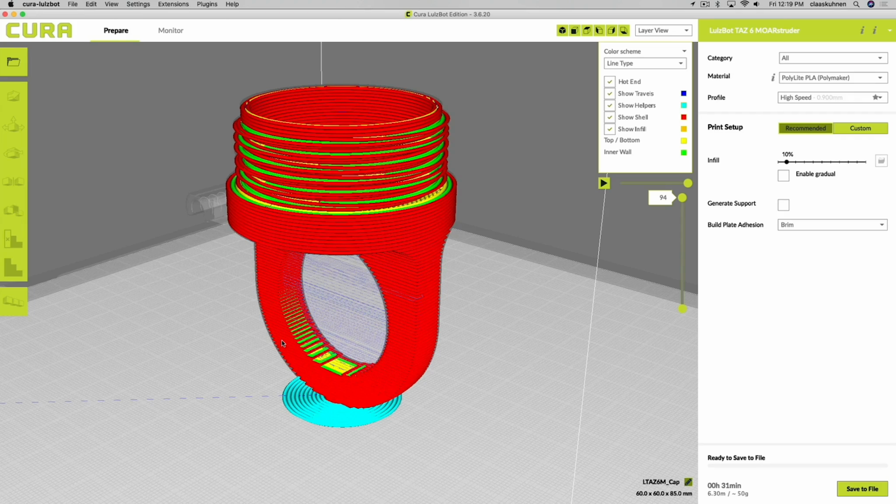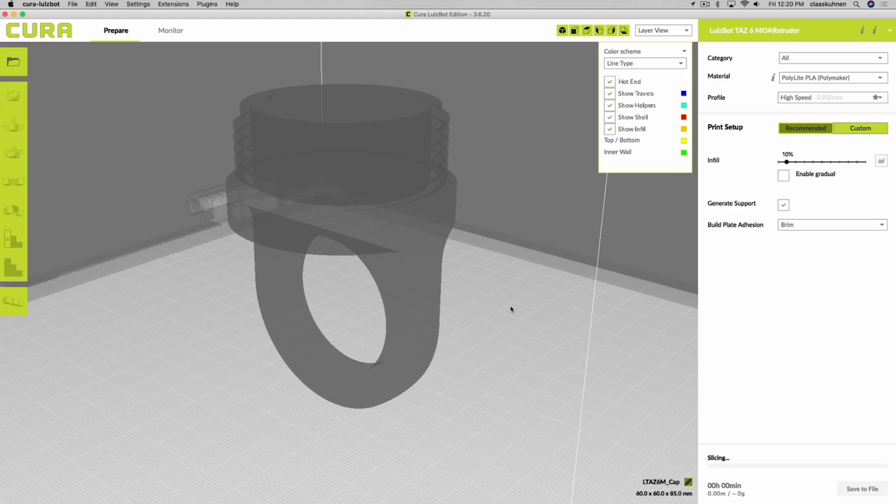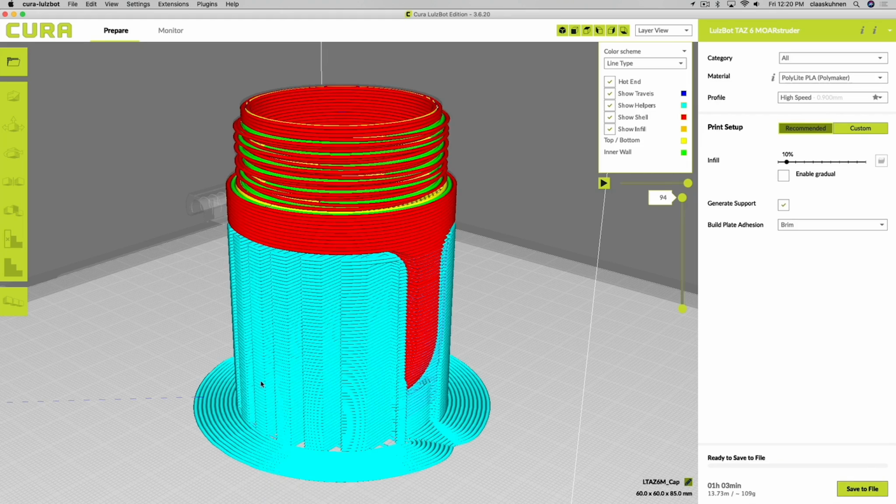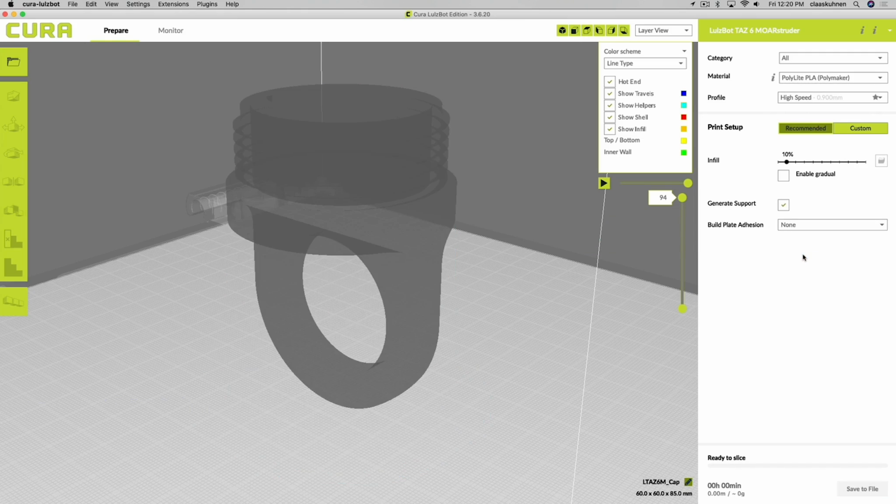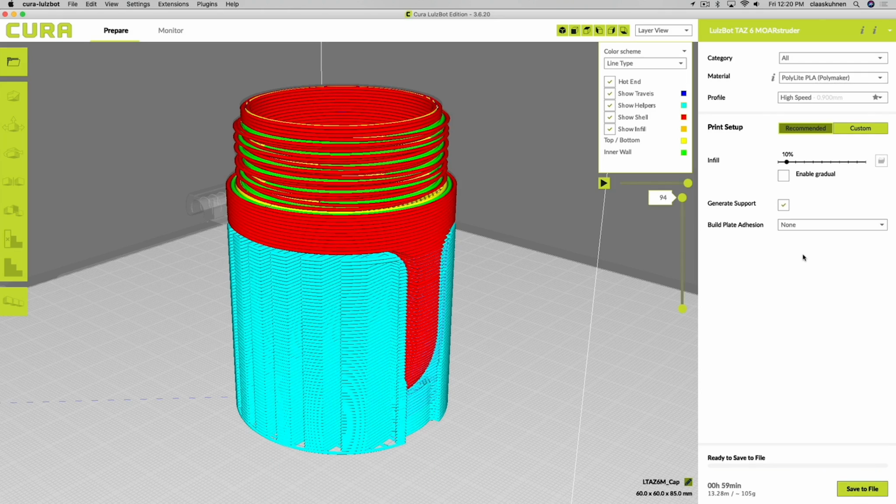And then this actually will help to create a bigger suction to the platform. And you see then when I create the support in this case here, this is a much bigger platform and the brim goes around. So in this case, I don't really need the brim at all. So I could remove it. Very good. So talking about the support.